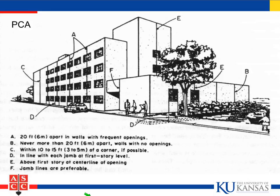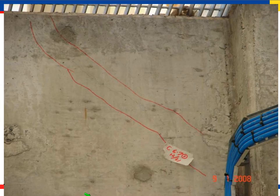Also, this is from this PCA slide. If you have exterior walls of a building, there are recommendations on where to put the contraction joints so that it looks nice and straight. If it's straight like this and you pick the crack locations, nobody's going to think it's cracked.